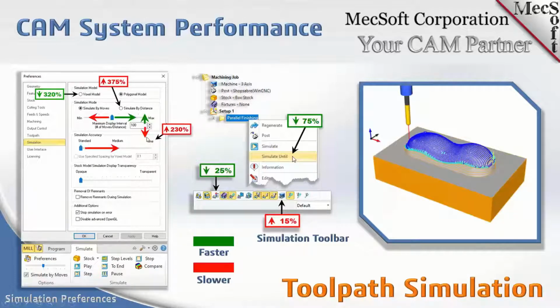I also mentioned the trick: if you want to bypass all this gobbledygook and cut to the chase, just right click on your toolpath operation and pick simulate until. That bypasses everything. It doesn't show you anything until the end. It's going to calculate, and then it's going to show you the final simulation model. So if you're worried about time, go ahead and use simulate until.